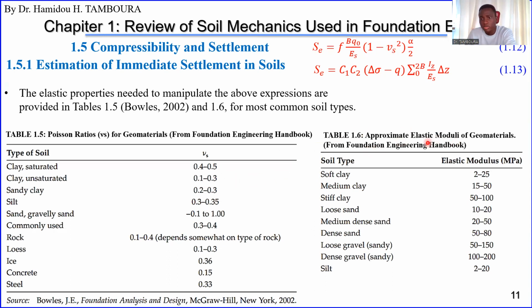And for the elastic modulus, the Young modulus, here are some ranges for different types of soil: soft clay, medium clay, stiff clay, loose sand, medium dense sand. This is just an example. If you don't have the possibility to estimate the exact value of these parameters, maybe you can use this table.